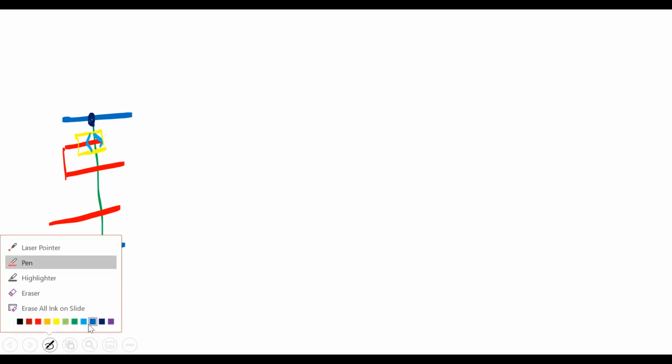Now notations. Color changed, I will take this color. So VDD, ground. This is the input A. This is the output Y. This is the source, drain, gate. This is the drain. This is the source, and this is the gate. This is the NMOS inverter stick diagram.